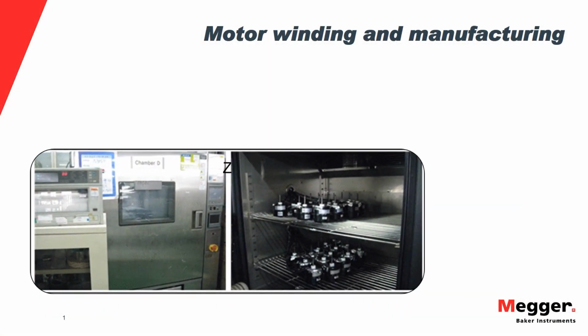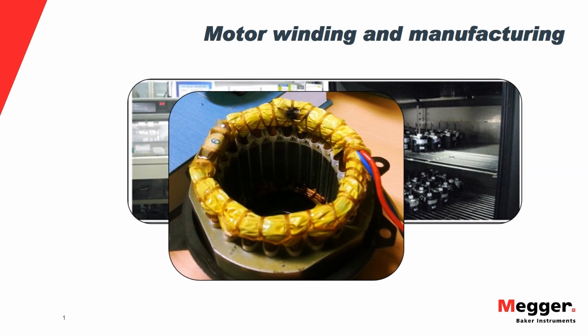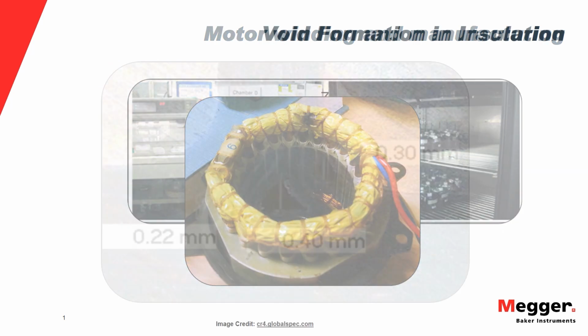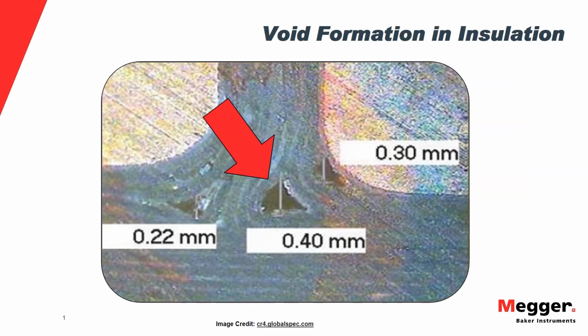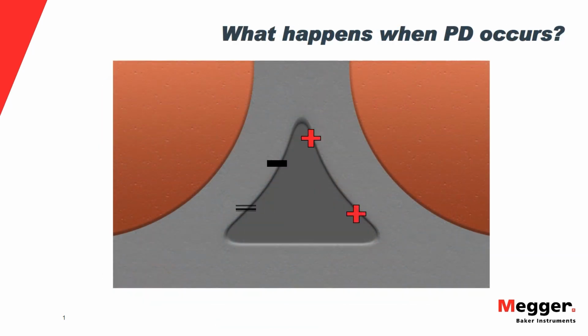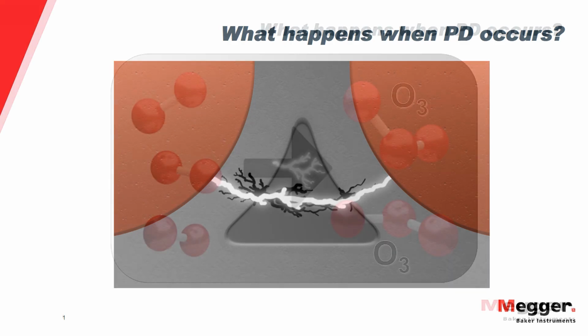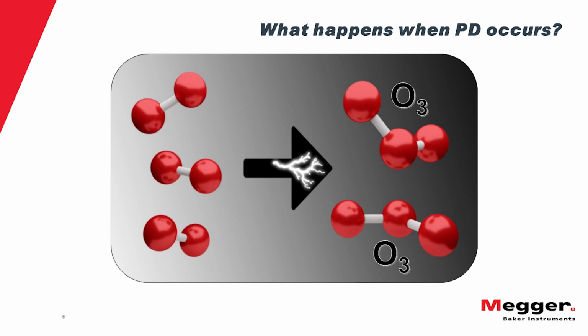During the coil winding and motor manufacturing process, it is possible to develop areas that are conducive to partial discharge. Bubbles or voids in the insulation can lead to such a condition. During the operation of the motor, these voids can become charged. At a certain charge level, this interspatial void will discharge itself. This discharge is not to ground or between conductors, but within the local void itself. These discharges can produce chemicals which are destructive to the insulation system, causing its life to be reduced.